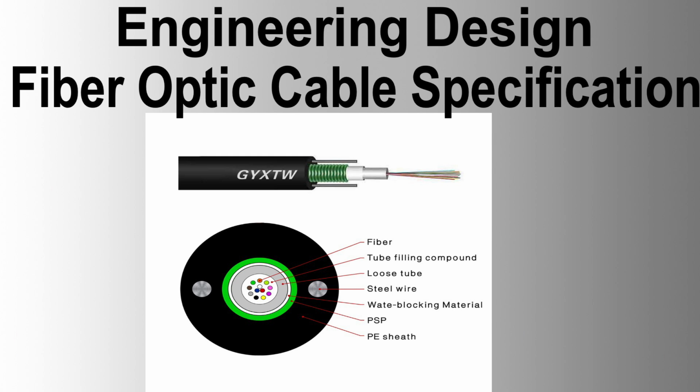Handling and storage. Avoid standing on the cable, and do not allow vehicles to drive over it. Cable drums should be rolled only in the direction indicated by the arrow on the drum, and should not be laid flat. When lifting the cable drum, use a spreader bar to avoid inward pressure on the drum flanges. Ensure cable ends are sealed with a heat-resistant sleeve to prevent moisture ingress. Pre-installation testing. Test the cable at the site before starting the laying process, and record the test results in the approved test sheet format.